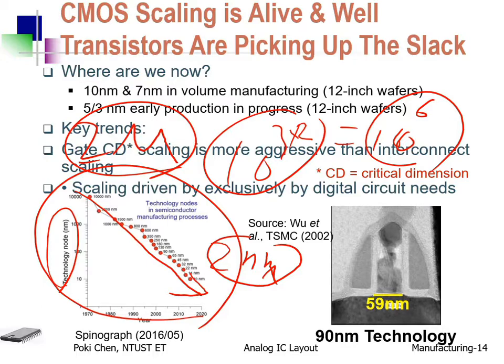For a truly automatic one, you need the help from LiDAR with laser. But for the semi one, radar will be good enough. It can help me to trace the car in front of me, to speed up or to slow down all the way to the speed I set. And it can also help me to steer my wheel to control the direction of the car.